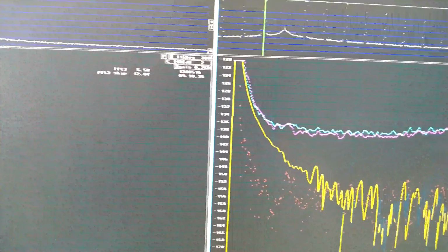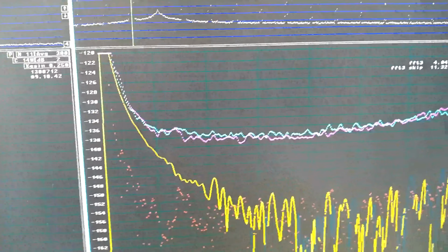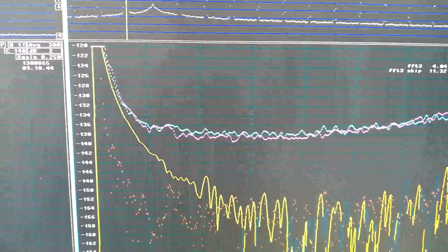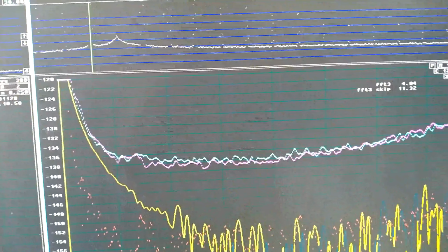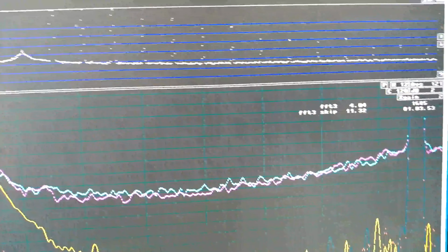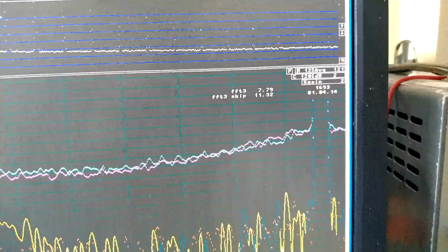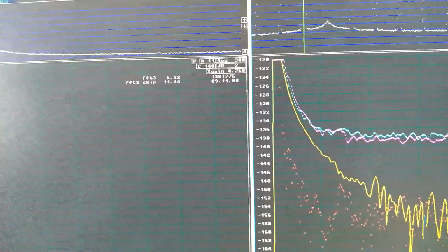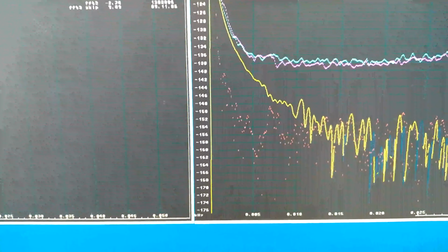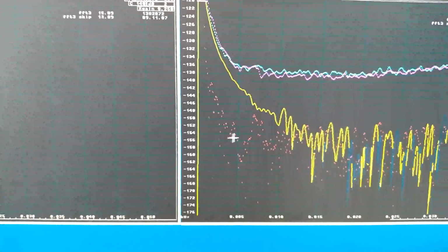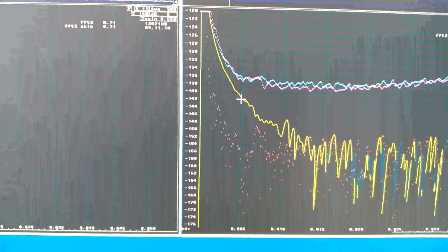I had set the SDR IP instance of Linrad to elevated priority. That caused the sound card instance to stop working. It just froze. So when I came back, it didn't show any reasonable result. Now that was 1 hour ago. It has now been running 1 hour, 4 minutes. And that is enough to get a good reading at 5 Hz. So 5 Hz, it is here. And what I see is minus 142.